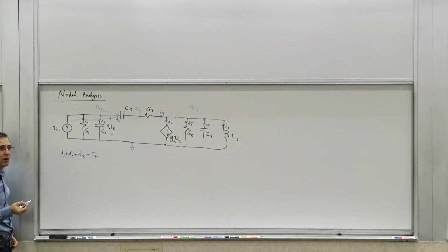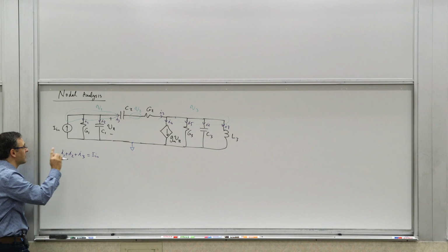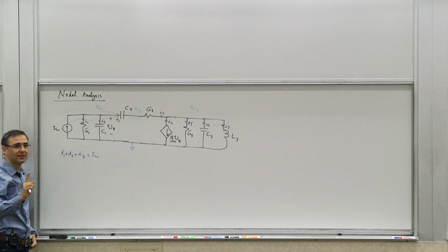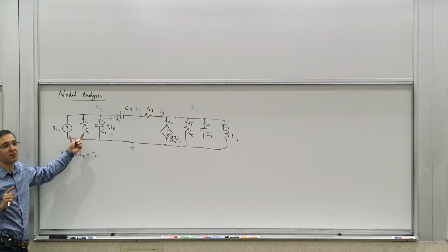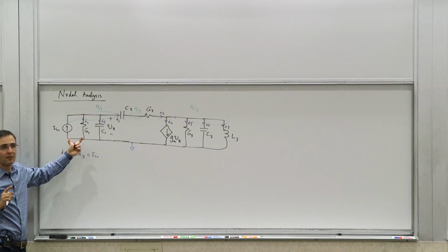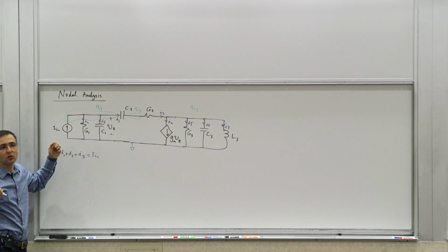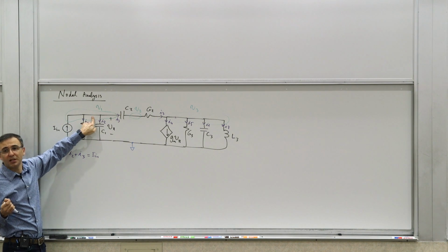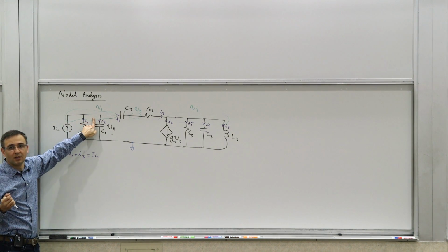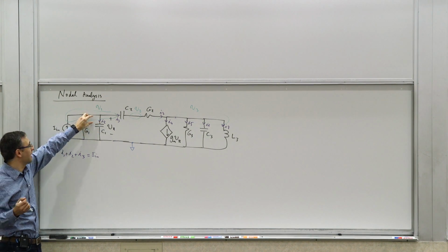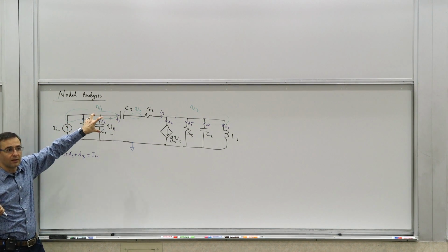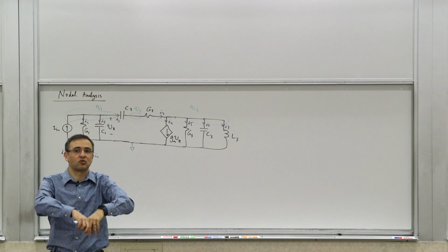That's the Kirchhoff current law, which comes from conservation of charge, and the fact that the dimensions are much smaller than the wavelength, which basically from Maxwell equations you can show easily that there's no charge accumulation on the node. You need that second condition that the dimensions are much smaller than the wavelength for this to hold. Otherwise, you can have charge accumulated on the node, at least temporarily, or charge being drawn out of the node.